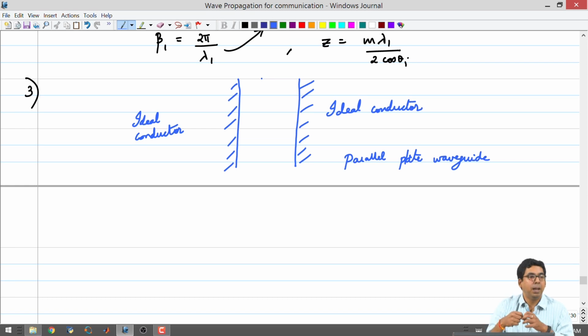Why one would use a delay element involves a lot of factors. For example, if you have two signals and you want to make a logical operation out of them, like AND, OR, NOT, etc., you may get one signal on one of the input pins first, and you want to wait to make the decision after the second signal also arrives at the second pin, which means that you want to delay the first signal with respect to the other, so that both of them arrive at the same time, etc.